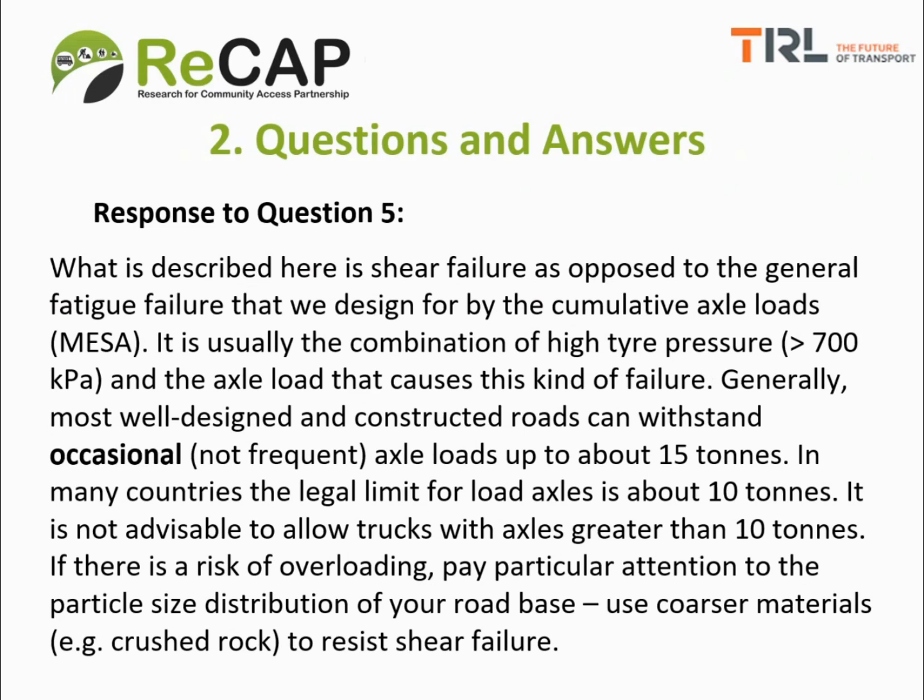Our response is that what is described here is actually shear failure as opposed to the general fatigue failure that we designed for by the cumulative axle loads, often abbreviated as MESA. It is usually the combination of high tire pressure, well in excess of 700 kilopascals, and the axle load that causes this kind of failure.